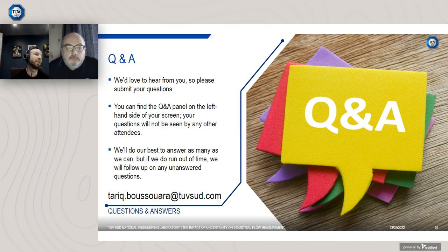You can obviously manipulate it and click on anywhere on the object, and it tells you exactly how much material has been lost. And so that is probably one of the better methods, but it depends if you can get access to the component. So things like a bit of pipe, you can't get access to the internal surface unless you slice it in half. So it's quite difficult to do that. So that's where we might do weight loss or visual inspection once we've subjected it to erosion.